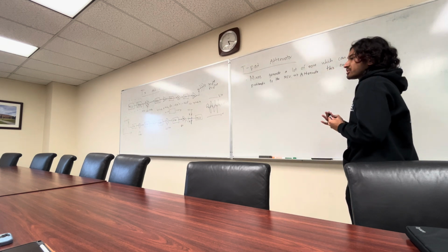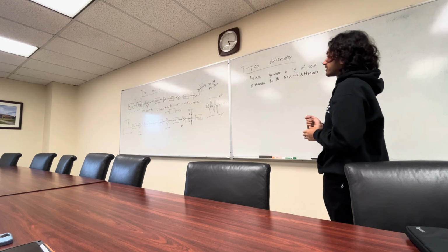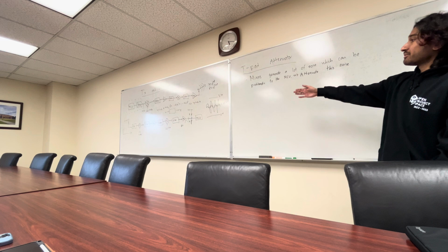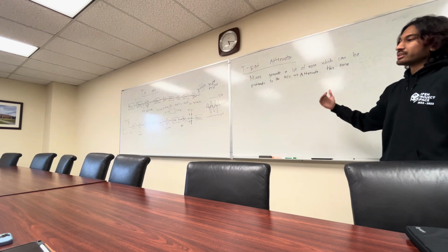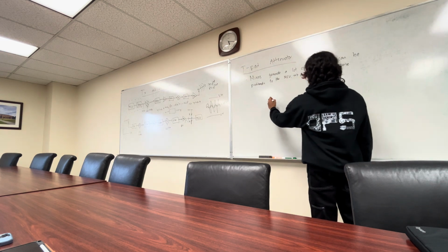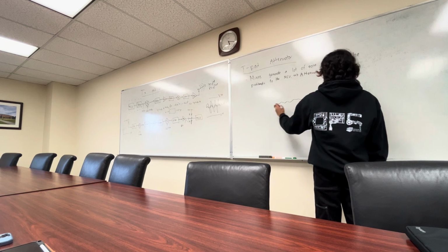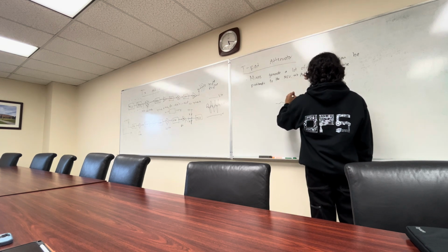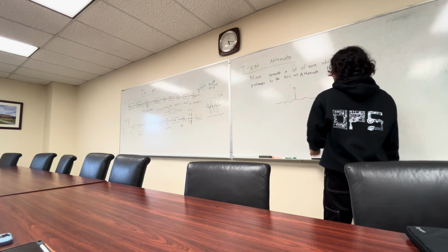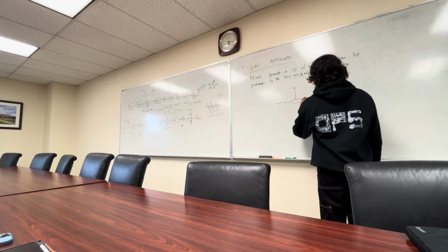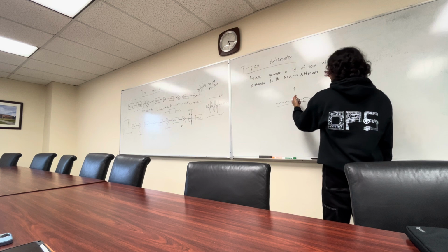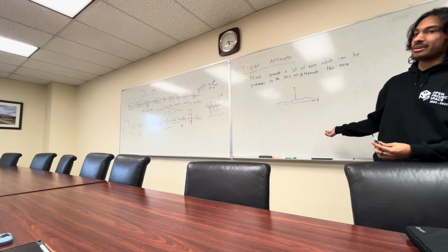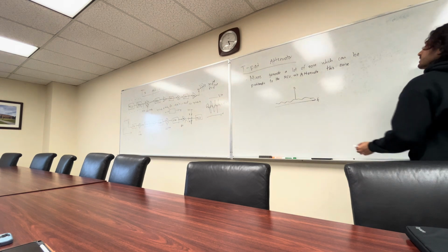So when we talk about components, we like to also talk about their noise. How much noise do they add to the system? At the end of the day, we want to transmit a signal and receive it. If our signal looks like this in the frequency domain, say this is F, and this is your noise floor, our signal is pretty high above the noise floor at the receiver. So you can pick it out and actually extract meaningful information out of it.